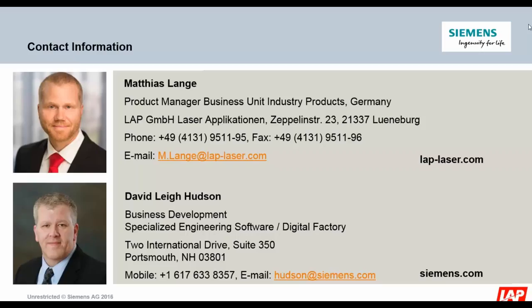But even from a manufacturing standpoint, a manual layup process can be done differently. One of the things that we do with FiberSim is allow somebody to define that manufacturing layup process, and then we can communicate that through things like markers that allow somebody to understand what the manufacturing process is supposed to be with the laser projection system. So we use the manufacturing producibility in defining that process to then simulate what that flat pattern is going to be and generate the flat pattern. That's what ends up being cut.